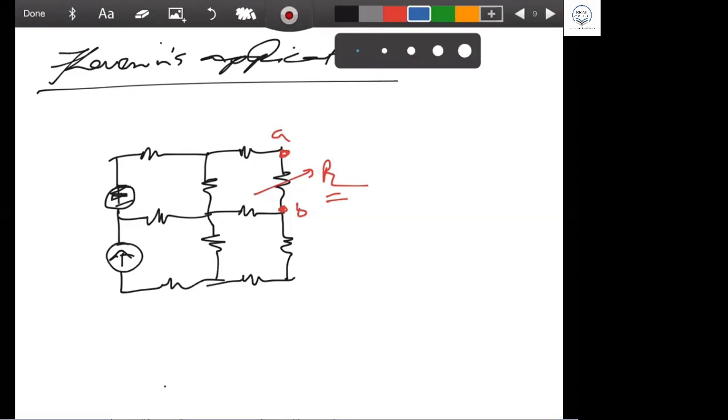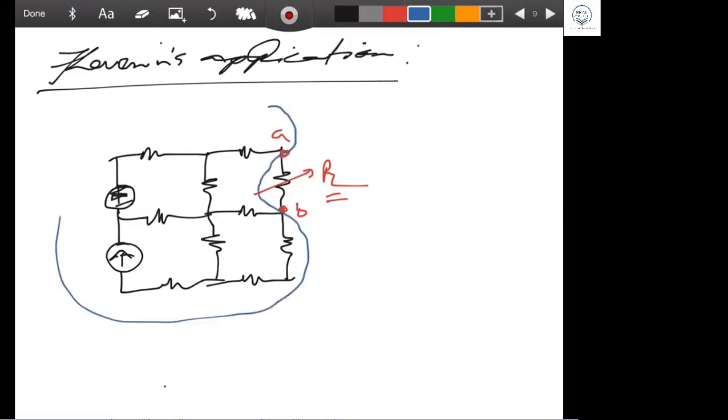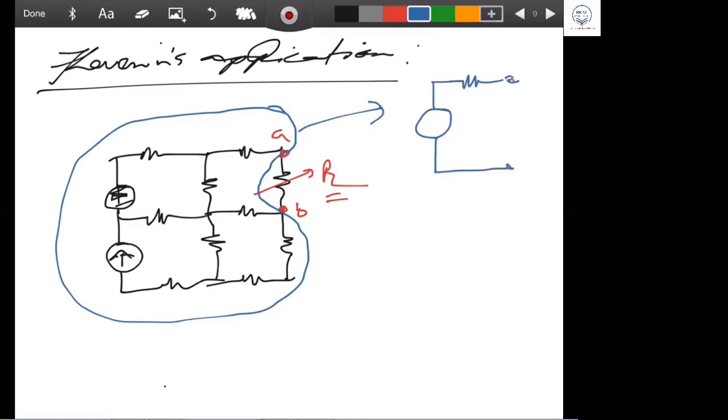You can remember this, right? This is the way you simplify the whole complex circuit and make a simplified form. And what is the name of this form? Thevenin. So we call it Thevenin's theorem. If you go for Thevenin's theorem, then we can connect RL back here. So your RL comes here like this, and this is your source, plus minus, E Thevenin, and this is your R Thevenin. Remember?